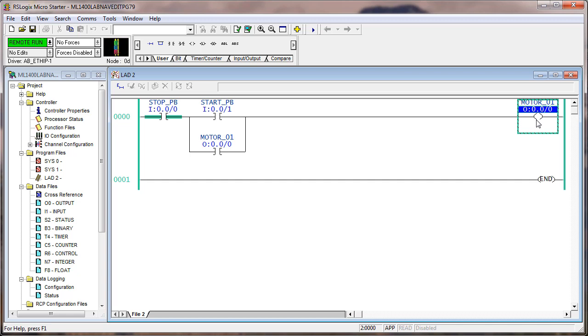So if you energize the coil on this motor starter, 4 contacts close. 3 of them close 3-phase voltage to a 3-phase motor, and the 4th one is probably not used, but it's there as an auxiliary contact if you want to turn something else on. So it could be a motor starter, and by the way, they don't call them motor relays, they call them motor starters because they also have motor overloads on them. If too much current is drawn, it will interrupt the circuit and drop out the starter or the coil.